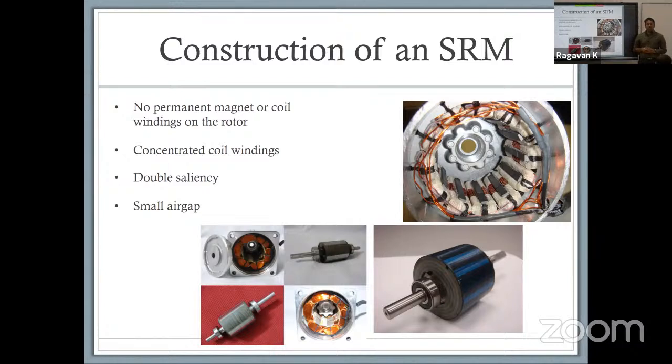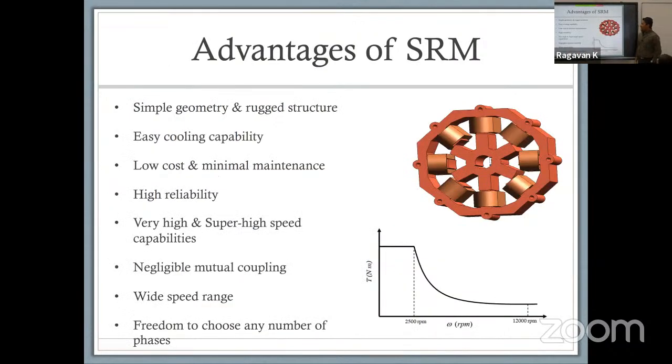This motor is known to have a very small air gap. That is both a benefit and a shortcoming. When you have traction motor drive type applications, the challenge tends to be that there are concerns about how much clearance you need to have for the motor to operate. But on the flip side, it gives you the ability to transfer power from the stator to the rotor very effectively. Like I said, as a result, it can cool easily.